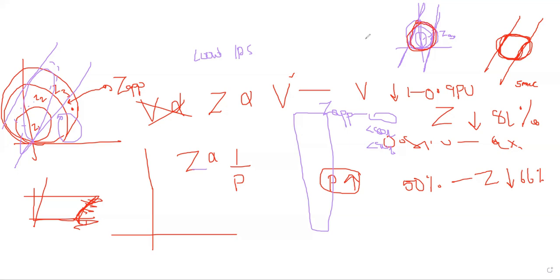But for the power swings, we have to bring this into the zone. And again, there might be a chance this is a fault, but it is showing as a power swing. So the relay will not operate. In this case, I am checking if it is a fault, there is a voltage drop. So if the voltage drop is there, then I am blocking this power swing and opening it. I am giving the relay full freedom to operate for this zone. Got my point?